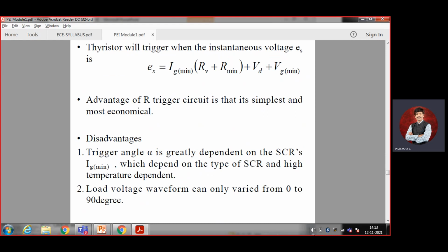The reason we are not getting the expected result in the lab is that there is no proper calibration of the components. We know 10K, but when you measure, it's not showing 10K, it's showing 9.8 or 9.7. So it's not properly calibrated to exactly 10K. Theoretically we say it is 10K, but practically we are not getting 10K. So we get some fluctuation in the outcome, but it is acceptable. 10% is acceptable.